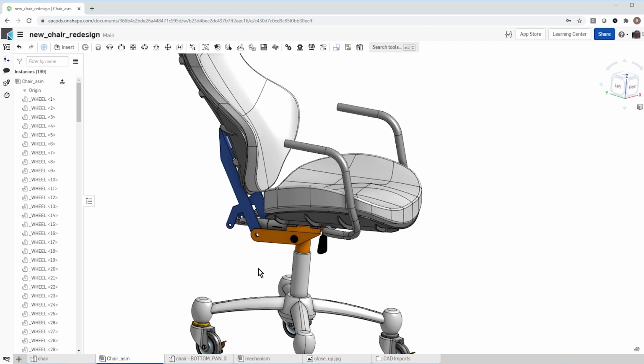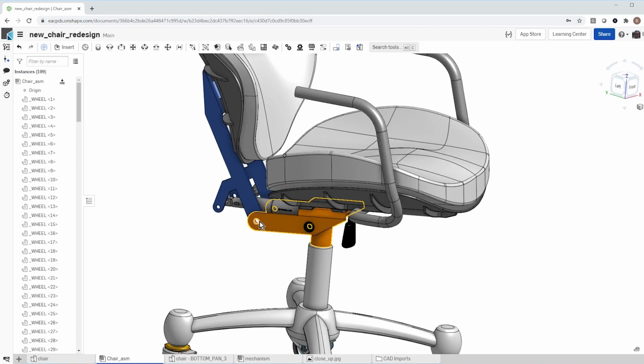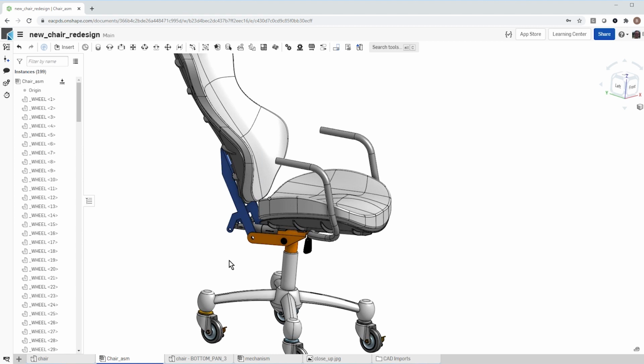Another thing that I would have done is, instead of doing a save as, you notice there's no save. You can look in all the menus in Onshape. There's no save. Everything I do is preserved, so I can go back to any point in time. But the thing is that I would have done a branch. So with this design, I would have said, let's just branch off and make this new version. And then when I had the new version, I could say, let's merge that in with the old one and replace it. So instead of me doing a delete and reassemble, I would just merge this branch in and things would have updated. So again, that would save me even more time.